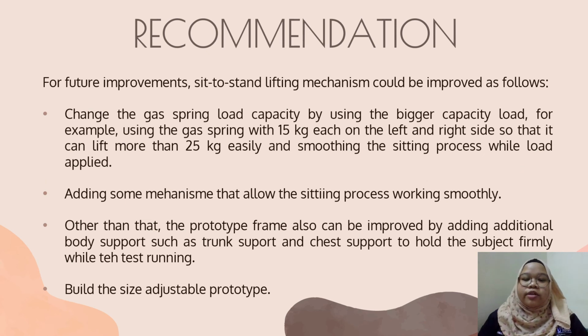Recommendation. For future improvement, the seat to stand lifting mechanism could be improved as follows. First, change the gas spring capacity by using a bigger capacity. For example, using a gas spring capacity of 15 kg on each left and right side, so that it can lift more than 25 kg easily. And then add some mechanism that allows the sitting process to work smoothly while load is applied.